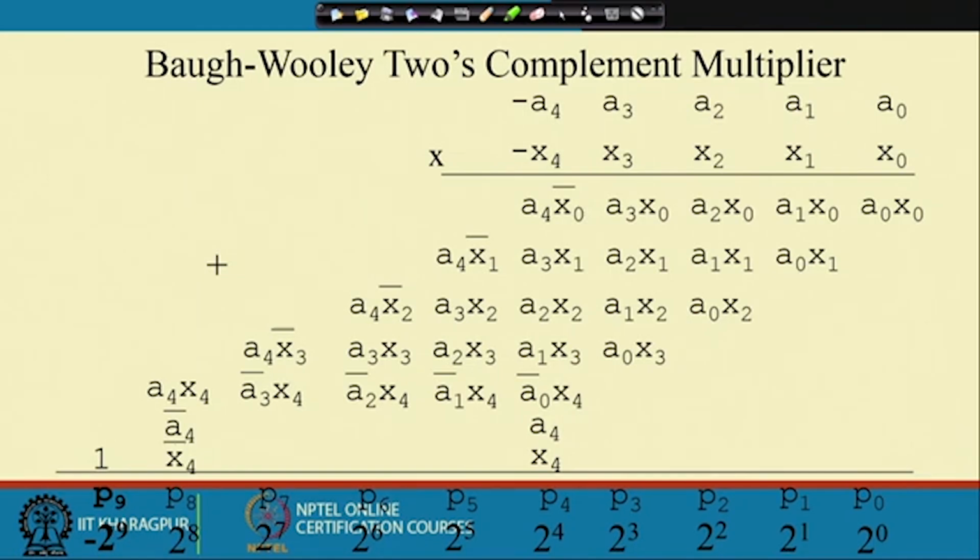So, if I am increasing the depth, as I am getting the maximum depth over this particular position, I am increasing the delay for this particular multiplier. But as I have considered the 2's complement multiplication method, I have a multiplier which will produce results in 2's complement number representation. So, at that time I need to do this. There is no other way out to not use this A4 and x4. So, I have to use this to get the proper result.